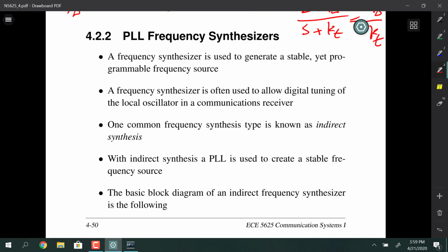A more contemporary version of what's called indirect synthesis, which is when you use a phase-lock loop, is the direct digital synthesis, or DDS. The generators that we have in the COM lab are DDS types. There are special DDS generators, and I don't know all the ins and outs, but Keysight calls it true form, which is something that's got better characteristics than just a simple direct digital synthesis.